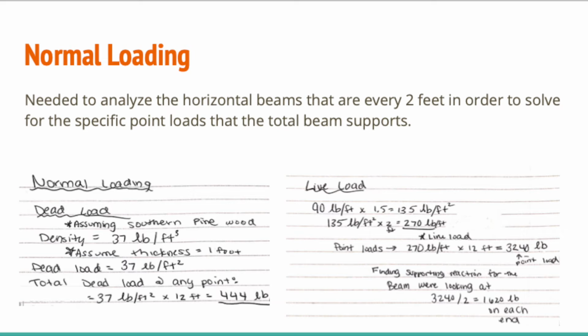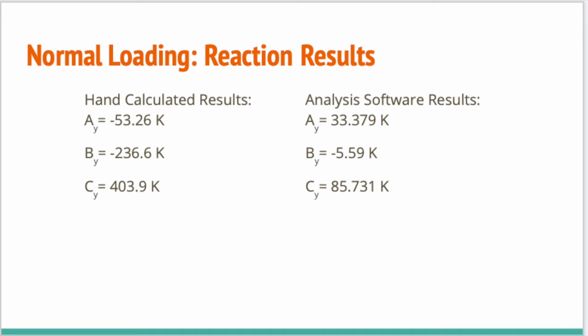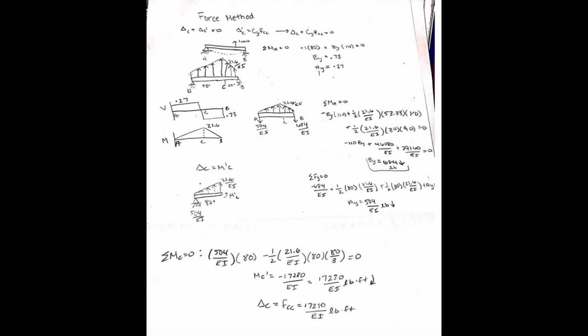We used the force method to solve for the reactions at the pin and at the 2 roller supports. This method includes drawing influence lines and removing a support to make the structure determinate, and placing a virtual load at the point where the support used to be, and coming up with compatibility equations that enable us to analyze an indeterminate beam as determinate.